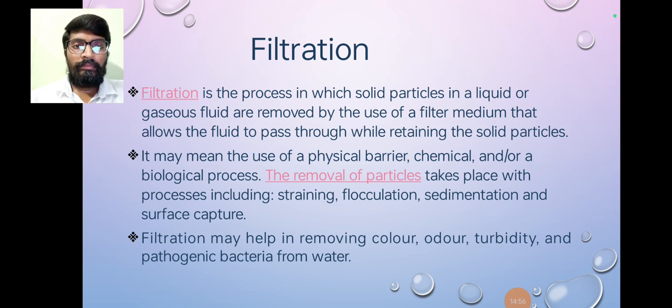So the next stage is filtration. Filtration is the process in which solid particles in liquid or gaseous fluids are removed by using filter media, which allows the fluid to pass through while retaining the solid particles. The filter media is made up of sand particles and quartz aggregate, with sizes of 20 mm, 40 mm and greater than 40 mm.